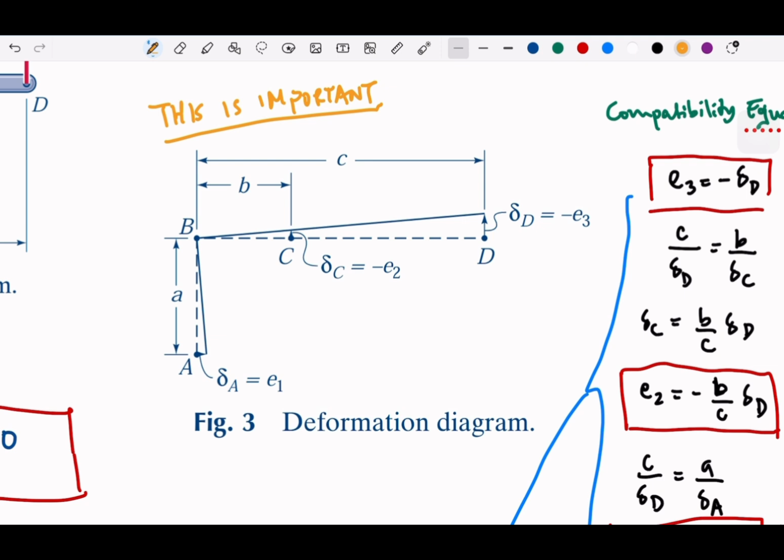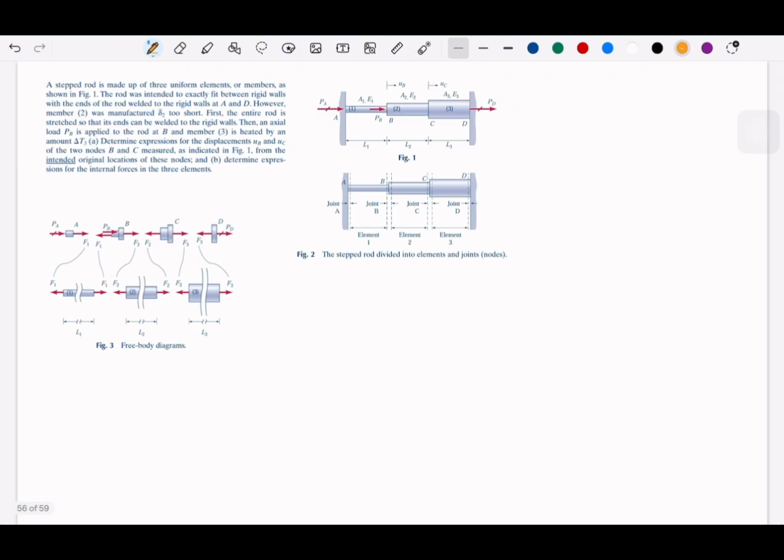that ratio, especially in this problem, because every time you have a statically indeterminate axial deformation, which means the information is not enough, you need to assume another equation that is set up based on the deformations. It could be the total elongation is 0 because of the wall. It could be deformations like this, or I will show you in the next part. Or if we have maybe not-fit situations, maybe the distance is too short. Let me give you this example.